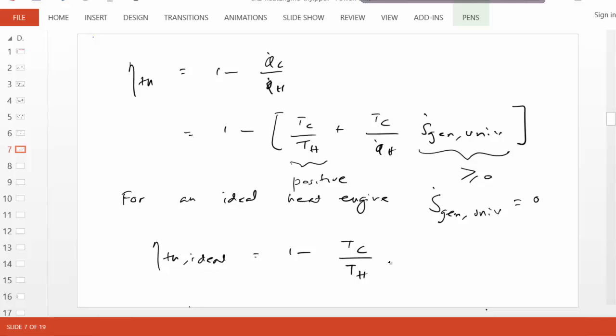Just think about it. All we need to know about a heat engine is its hottest temperature and its coldest temperature. The coldest temperature is the atmospheric temperature. You can reject heat to the North Pole or somewhere weird or inside a refrigeration system. So the atmosphere is our available temperature, and Tc is pretty much known, about 300 Kelvin.